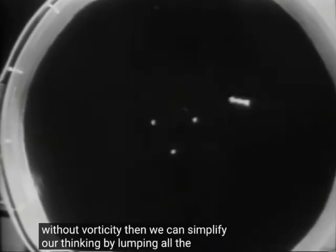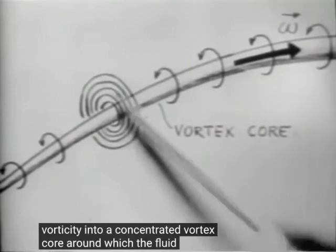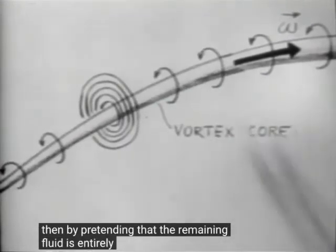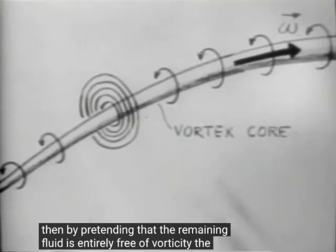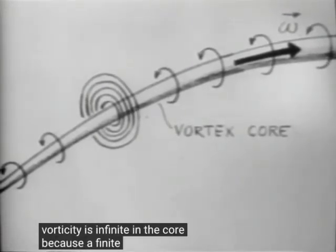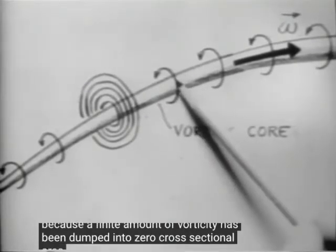Then we can simplify our thinking by lumping all the vorticity into a concentrated vortex core around which the fluid spins, and then by pretending that the remaining fluid is entirely free of vorticity. The vorticity is infinite in the core because a finite amount of vorticity has been dumped into zero cross-sectional area.